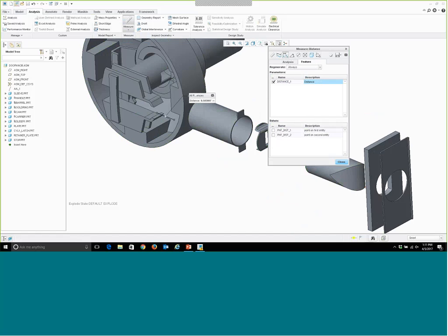A couple things that are really important within this dialog box can cause you trouble down the road. When you enter a name for this parameter, and you don't have to change the name, you can certainly keep the default name if you wish. But if you want to change the name of that parameter, there's two things. One, make sure you hit enter after you've edited the name.